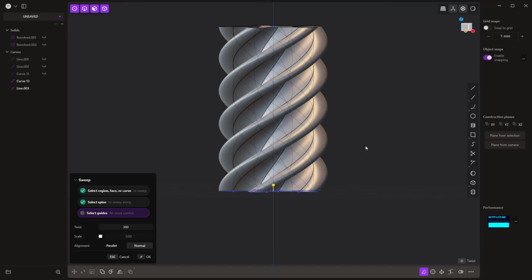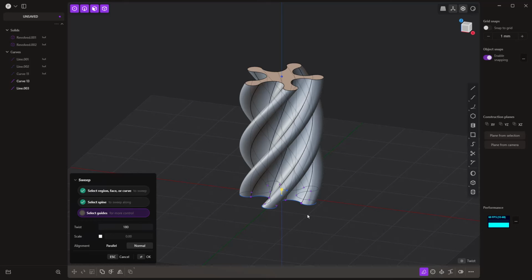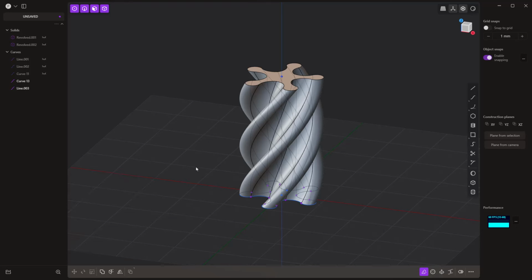If it gets too steep, or if it's past 45 or 50 degrees, then with an FDM printer, you start to have problems. So you need it to twist something, but it doesn't need to be extreme. So this is very easy to print here. 180 degrees will work fine. Again, 360 works okay. Past that, then you start to have issues with the layer lines building in awkward places. In some printers, you can get away with it. In most printers, I would just caution you unless you're very familiar with those limits. Then we're going to right click to accept.